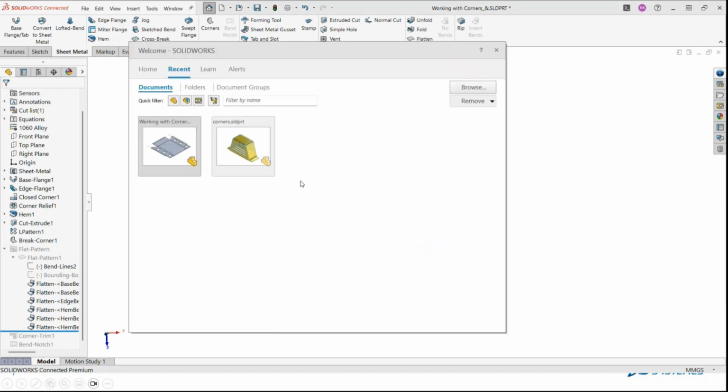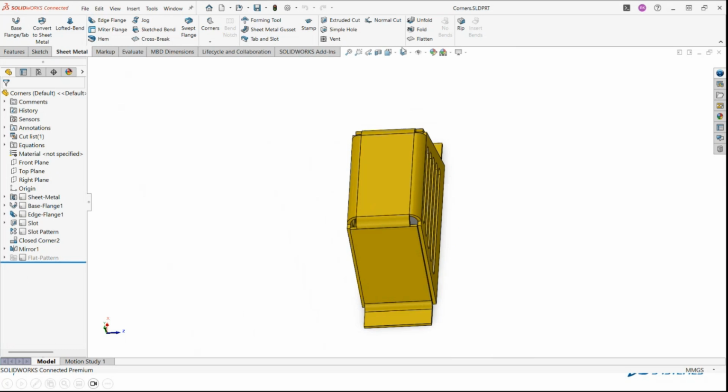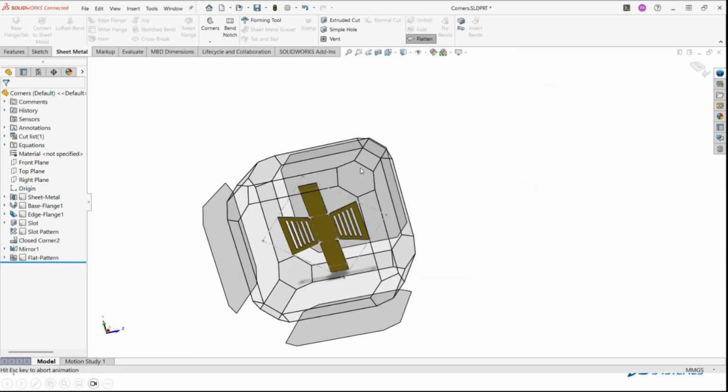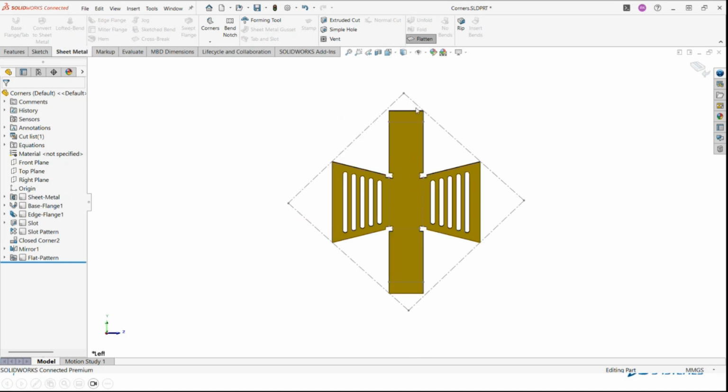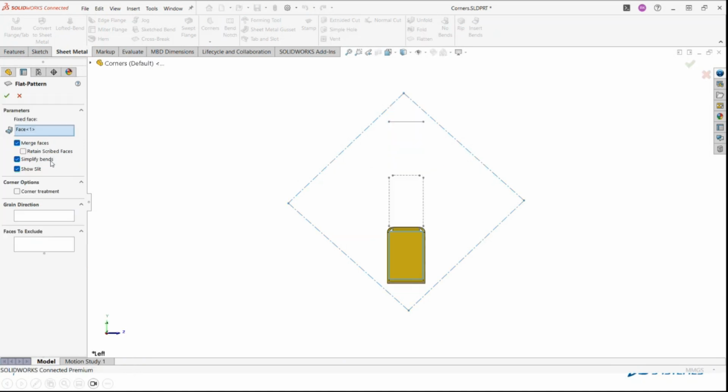But in flatten, we sometimes face some problems actually. So like this, what if I have created a part and it is giving me this kind of bounding box? Is it an ideal one? No, the wastage is more and it may concern my fabricator to cut out. So what we can do is go into the edit flatten option.